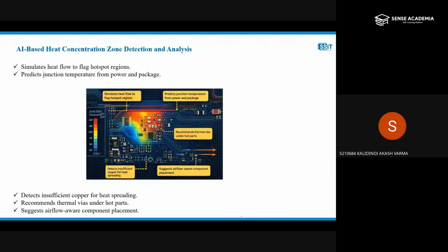And one more thing. Which zone is thermally affected, and whether we are taking actions for thermal reduction or not. If there are power related circuits and you are placing proper thermal compensation, the simulator will show it in green. If it is a thermally affected area, it will be highlighted in red.